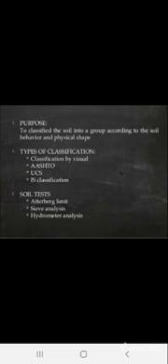So in the Atterberg limits we have to find the liquid limit and plastic limit of the soil, whether we decide that it is clay, sandy, or silty soil, right? In the sieve analysis, the major purpose is to find the grain size distribution, that is, what type and what size of particles of the soil are present there.